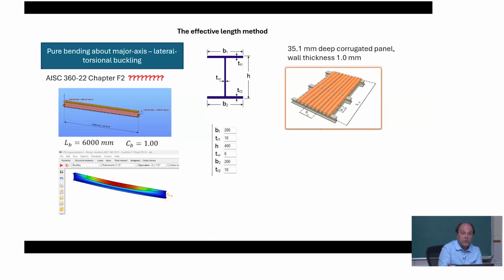Now in Eurocode, this is called S, a big S, probably for shear. I don't know what is in the Indian standard. If there is anything for that, it's probably not too much, because this is in the Eurocode 3 part 1-3 cold-formed code, which hasn't been implemented in India. But anyway, it's a mechanical something. That's the representation of the shear stiffness.